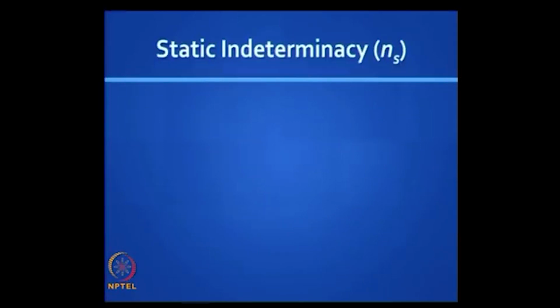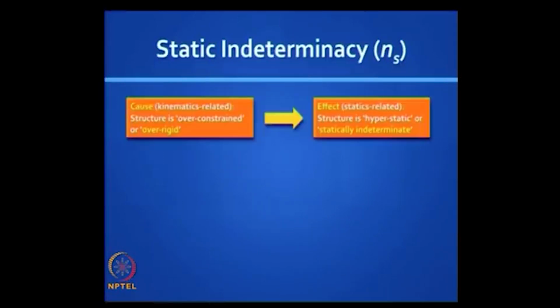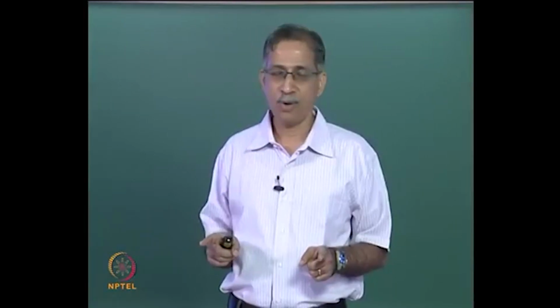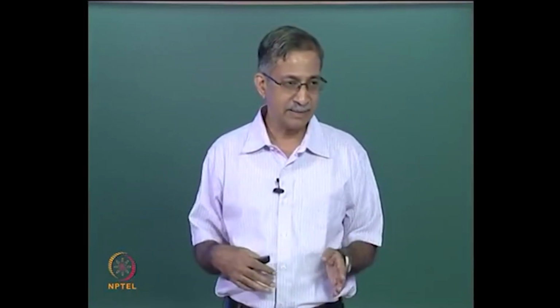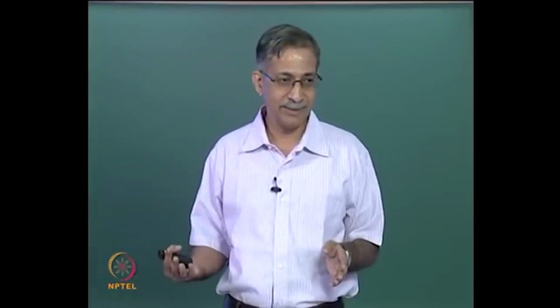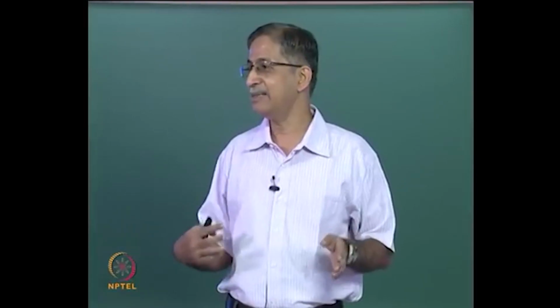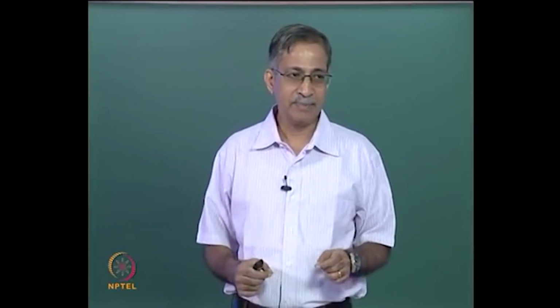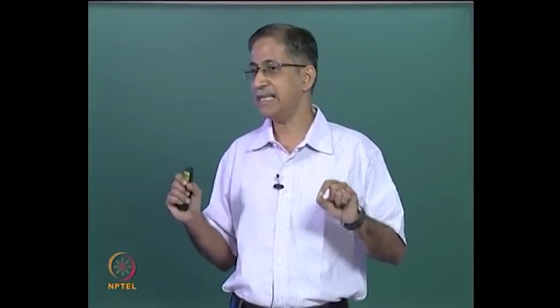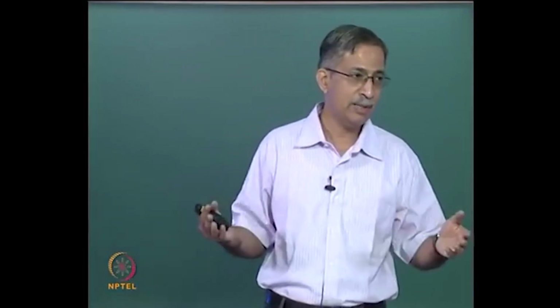Now we come to the topic of static indeterminacy, and it is important to realize that although we use words like statically indeterminate structures, as far as the structure is concerned, it is more appropriate to talk in terms of kinematics rather than statics. The indeterminacy is a problem that the analyst faces, it is no problem for the structure. The analyst finds it difficult to analyze a structure using simple equations of static equilibrium. So the statics is indeterminate. Statics refers to the force field.